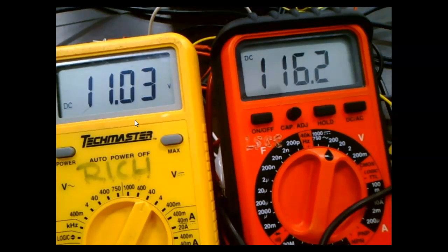You can see the voltage drop is doing what? Going up, which means the current is going up, right? And then the next thing I'm going to do is take freeze spray and spray it, and you see it goes down, right? So the amount of reverse current we get depends on temperature.